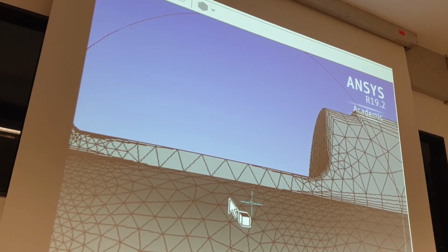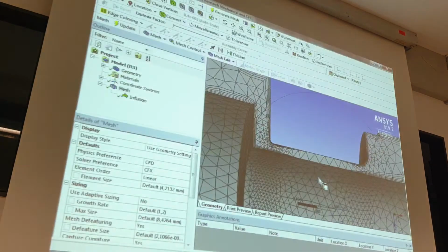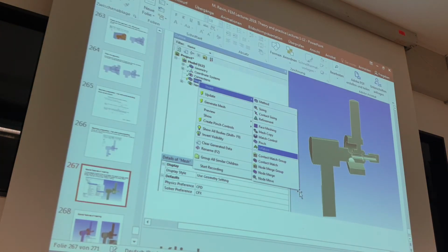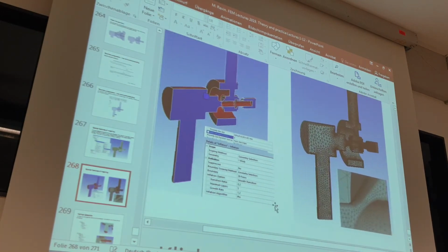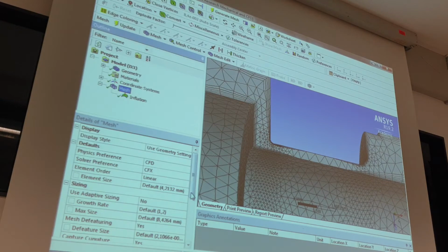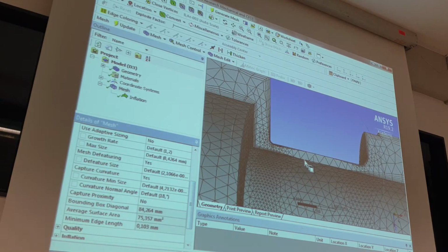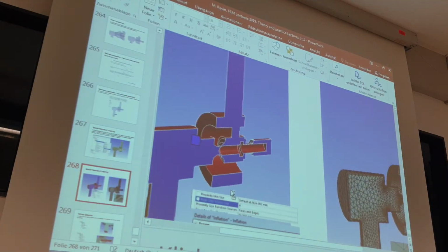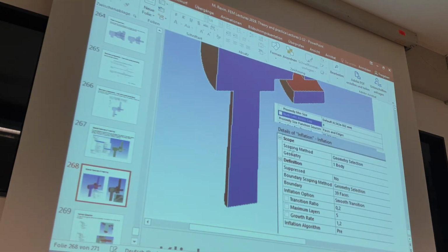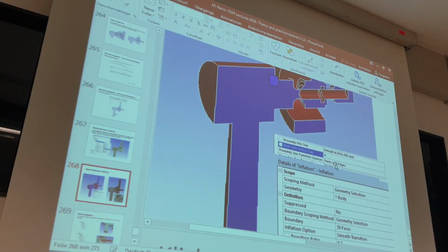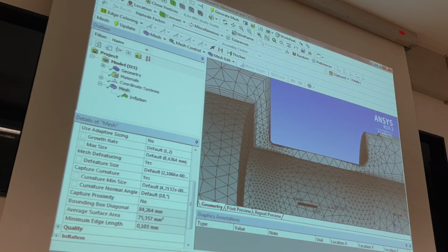So you see, this is not so good mesh, and we need, of course, now to do something to make this meshing finer. What it was in lectures, it was really fine, yes. What I always use is how we can create more elements between the inflation. You can create this with number of cells across gap. The program tries to create more elements between in the gaps, for example, 4. And this I did here.